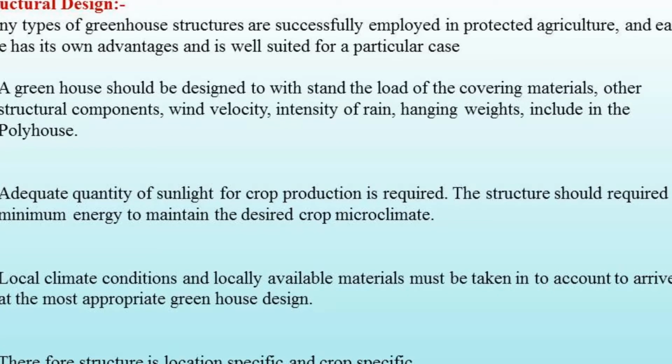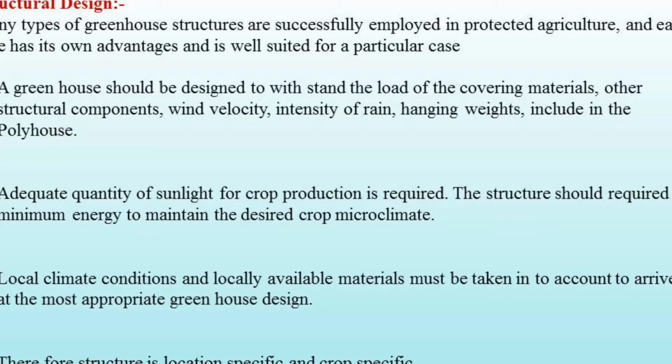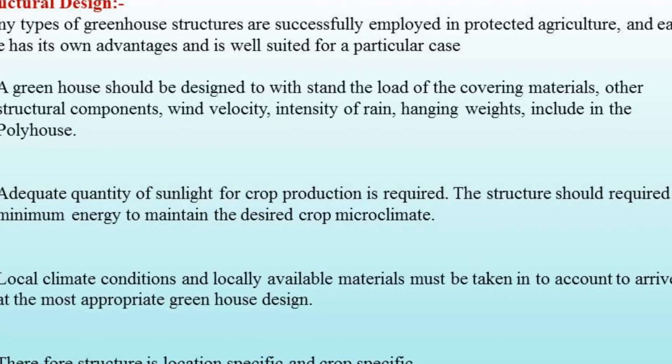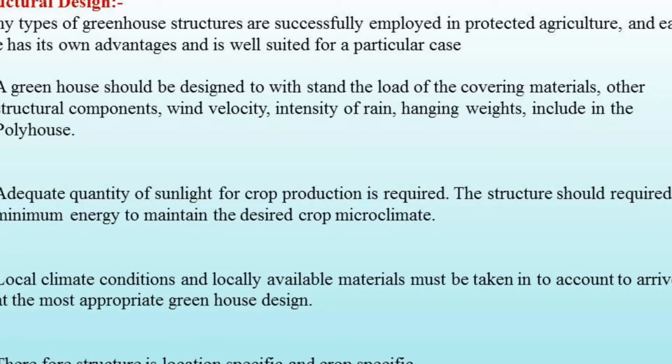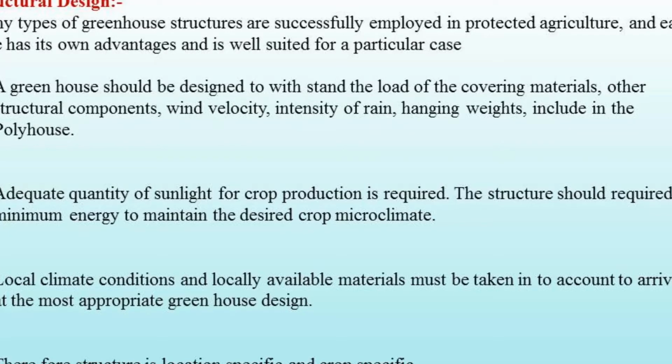Dead load includes the weight of all permanent constructions, cladding material, weight of heating and cooling equipment, water pipes and all fixed service equipment attached to the frame. Such types of loads come under dead loads.